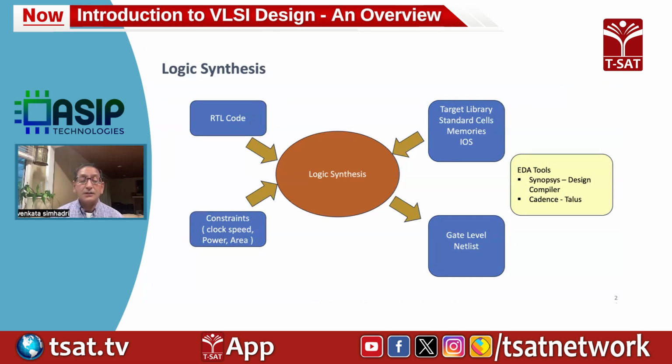This constraint file defines all the clocks that are in the design and how fast they are running. It also talks about any exceptions, like multi-cycle paths you have in the design, any other constraints, and any power and area requirements. So this is the constraint file.